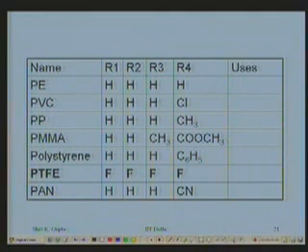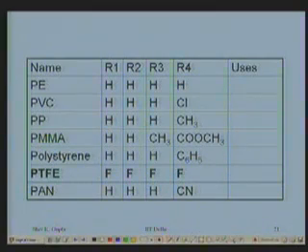Polytetrafluoroethylene is the next one. As engineers, as I already told you, all the side groups are fluorine, and we use it for its non-stick quality in bearings. We make sliding bearings, and we make rotating bearings. A steel journal can rotate in a bearing made of tetrafluoroethylene, that is Teflon. It will keep working with very small friction. It provides a coefficient of friction with steel